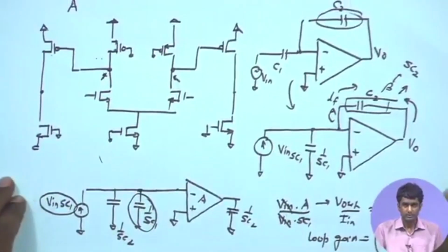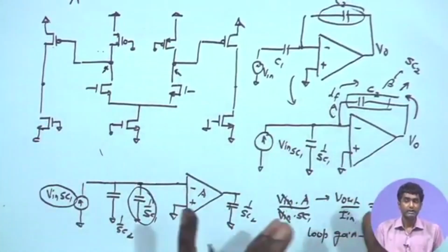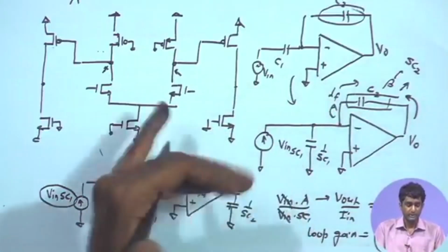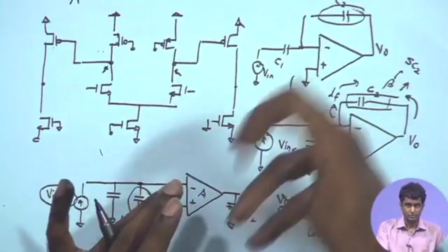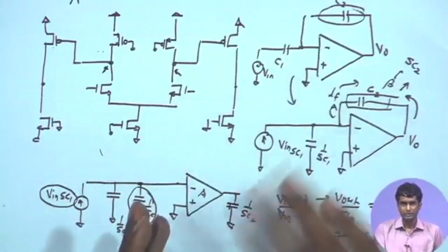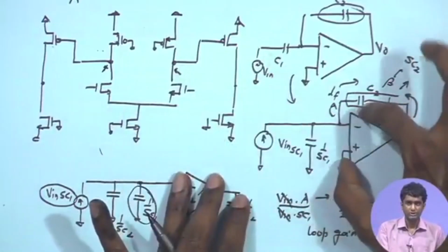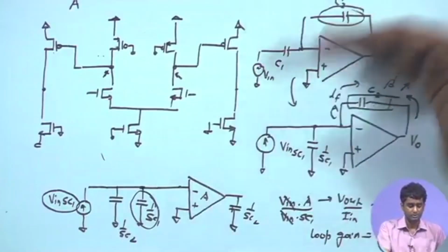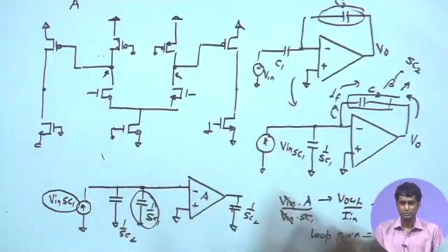And the only thing that we have to take note of is that we are using this amplifier overall as a voltage to voltage amplifier, but the feedback topology is a shunt. So, we are transforming the input source into an equivalent current source, and then doing the rest of the analysis. After that, if you assume that this is the given source and this is the topology, from here this overall derivation should not be a problem. The only thing is the initial step involved in transforming this input signal as a voltage to an input signal as a current.